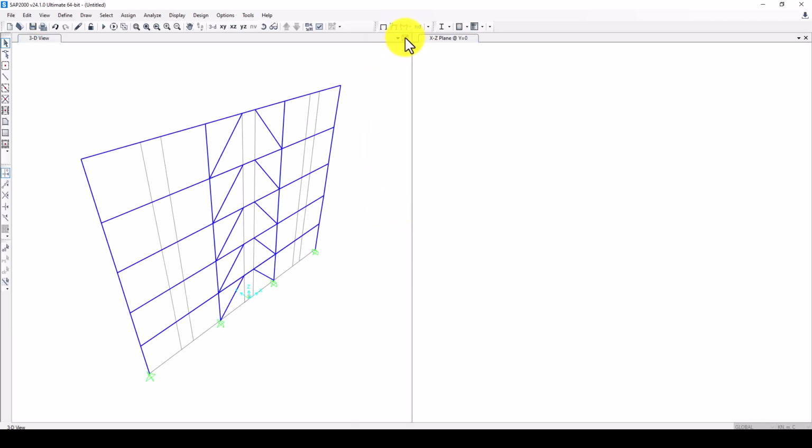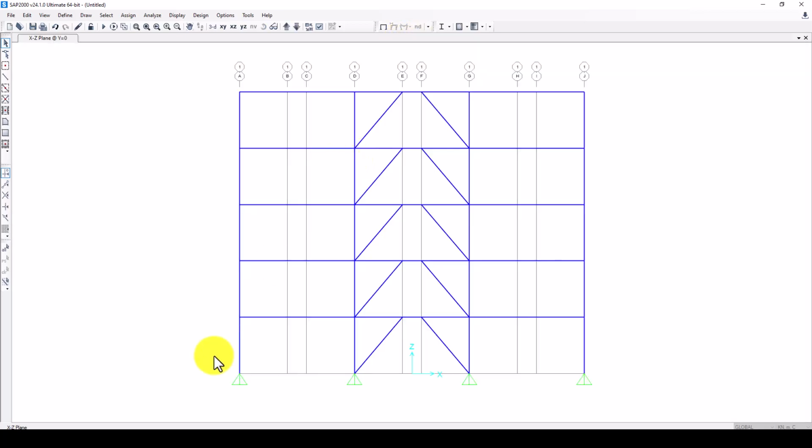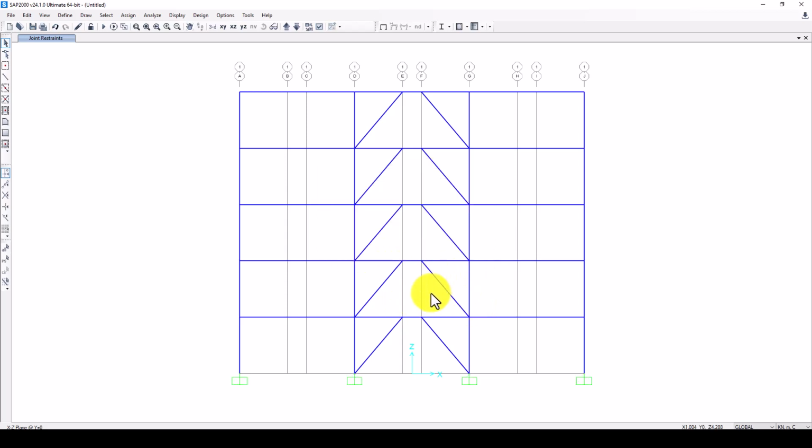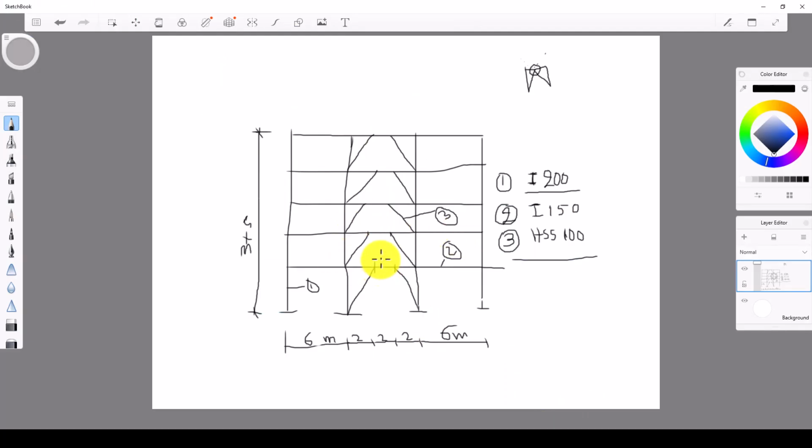I want to delete this window and just keep the 2D model. And the first thing is I'm going to assign the boundary condition. As we already said, it will be fixed. I should say that the length here is 1, and that means the gap is 1 meter. So the ratio is 2 and 1, and in case we can increase it there, and that's it. I should fix this. In my case, this should be 1 meter, not 2 meter.